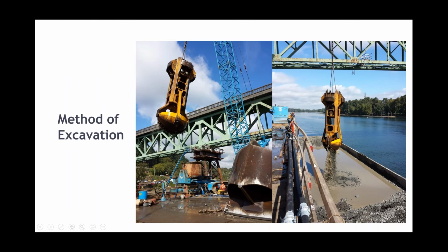The grab, you can see the grab, the same crane that the oscillator is attached to is operating this giant spherical grab. It goes down, takes a bite, comes out, swings over and dumps into the spoils barge. And then our field engineer gets his hip boots on and mucks around in there looking to verify materials that are being encountered.